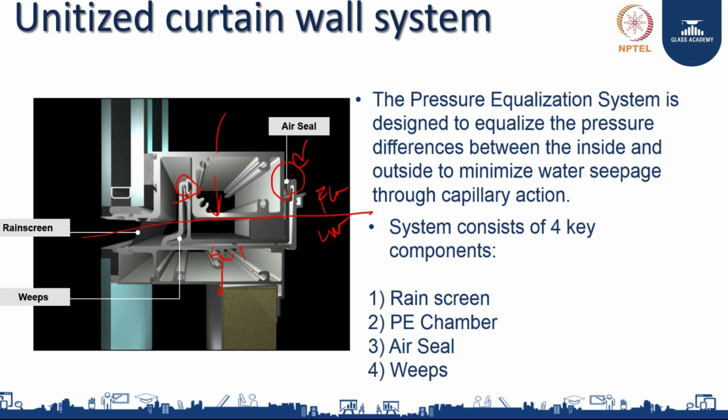If there is wind, for sure there will be water, but we have to control the water. Still there will be droplets of water which can get into the system with the wind, that you collect here. This is what we call a gutter. You collect the water like the gutter in your buildings. You collect the water there, but very negligible, because you are not letting too much water go into the system in the first place. So, they start draining off.